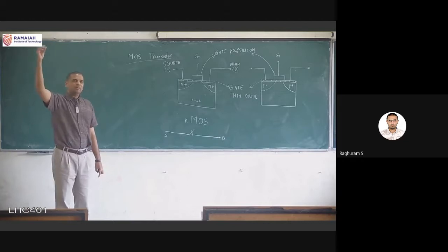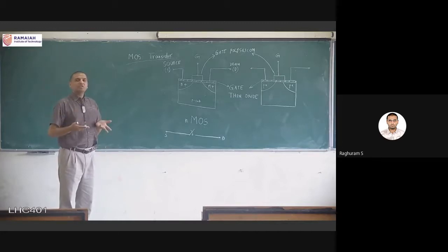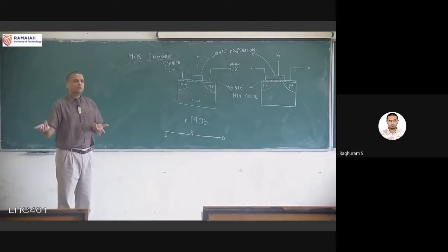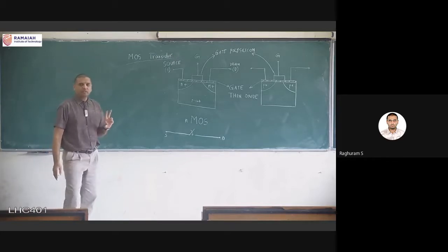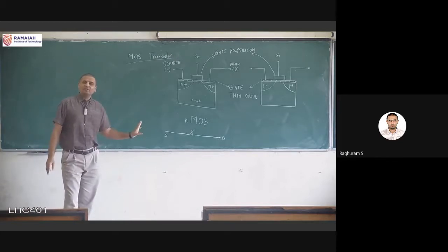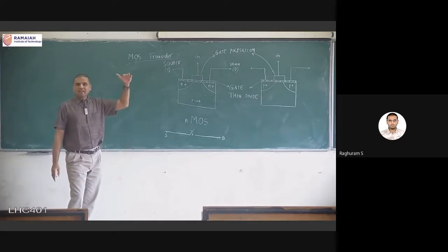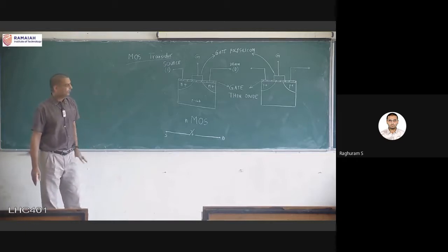Okay, we saw the pins in the fabrication. Those are only primary outputs, and there also we will not measure anything. It will just be at 0 or 1, because digital circuits means input is digital, output is also digital. So it will be 0 or it will be 1. That is 0 to VDD. Only two values of voltage for digital VLSI circuits: 0, which is considered ground, or the power supply, VDD. Okay, it might be 1 volt, 1.2, 1.5. That depends on the design.